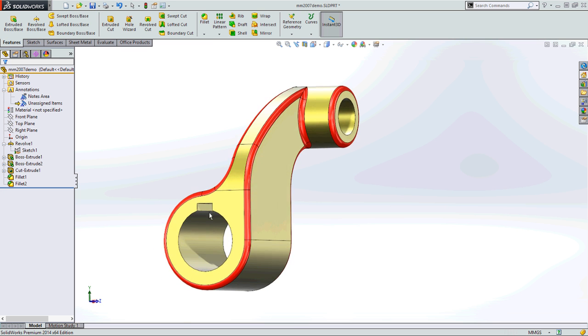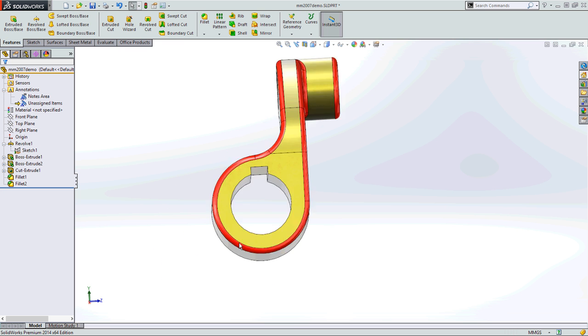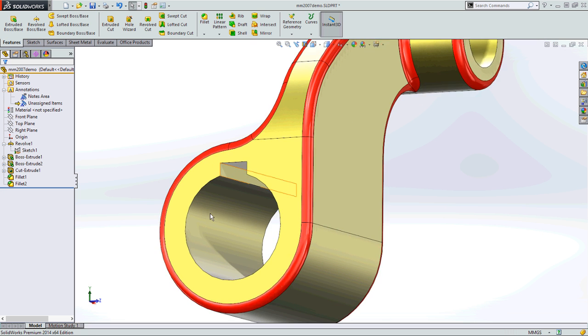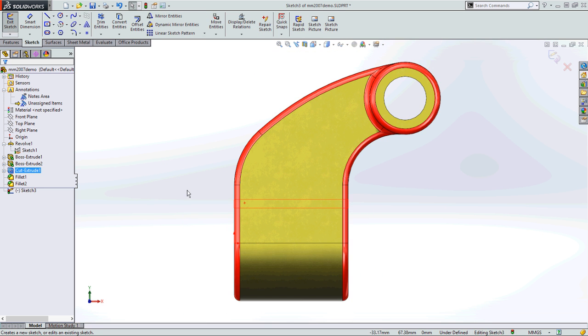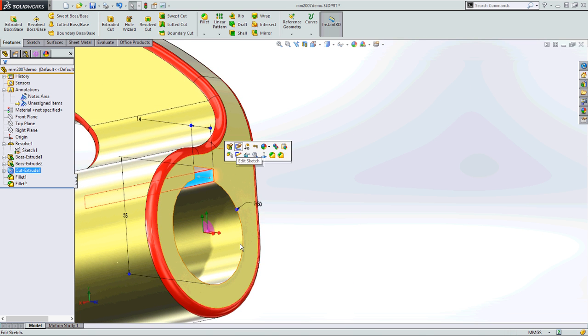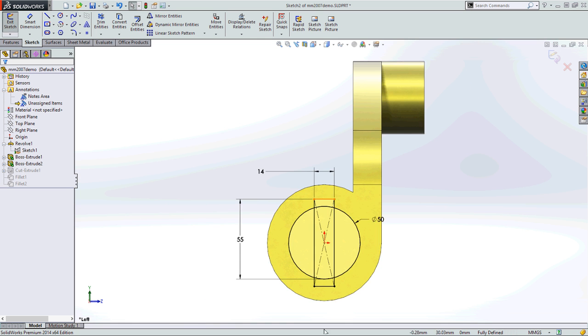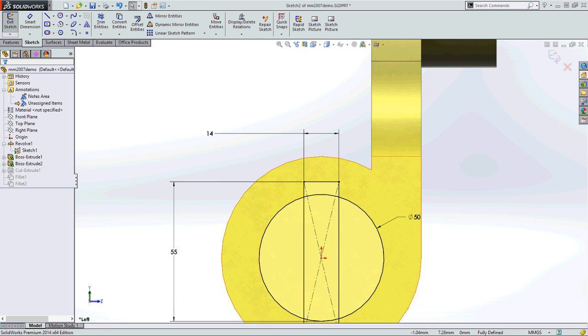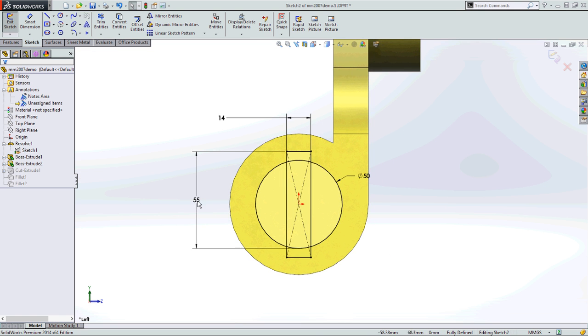Now, I guess the last thing we need to do is rotate this keyway over. And so how do we do that? Well, the first thing you'd probably think of is, oops, I don't want to sketch there, I want to edit that sketch. You'd go into this sketch and put an angle dimension on there. Well, this has vertical, horizontal. All these have vertical, horizontal. I'd have to delete all those off. I don't want to mess around with that.